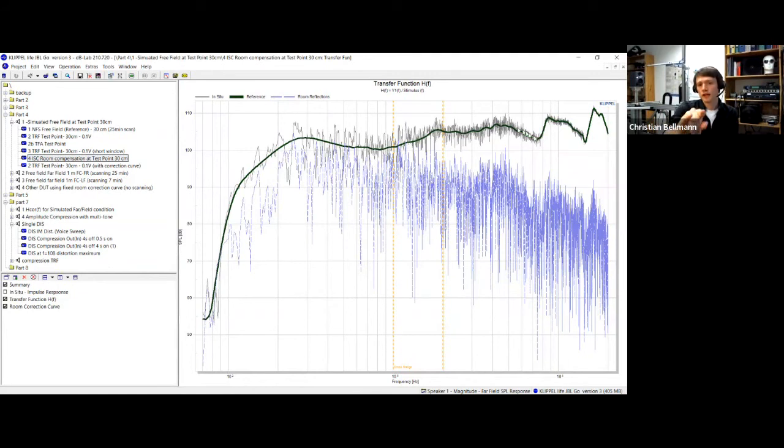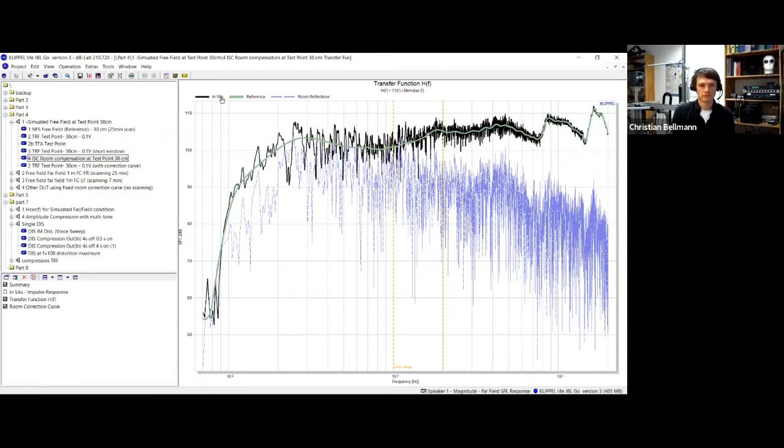And you have a crossing range between the two yellow dashed lines where we change from the free field reference curve to our windowing. For higher frequencies, we use the windowing; for lower frequencies, we apply our curve. And the gray curve in the background was our original measurement, which is called here C2.